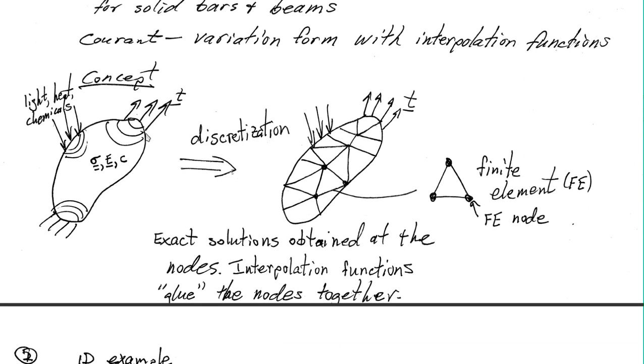Conceptually, what I mean in terms of a finite element problem is, imagine you have an elastic body, and perhaps this solid mechanics body responds to light, maybe heat, and chemicals. These will diffuse into the material. You may also apply traction. So this is an external load over an area, but applied on the surface. So you can imagine this is a force per area that'll generate internal stresses. You may also have internal electric fields, concentration due to these effects. And then down here I'm constraining it.